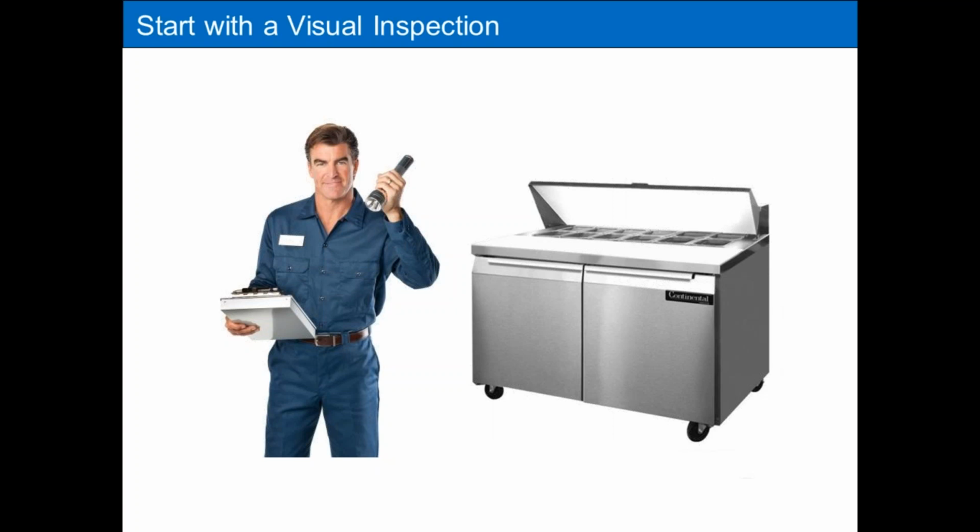A lot of times the cabinet's going to be in a food lineup. Pull it out, look behind it. A lot of times you'll see a plastic baggie right on the condenser. It's sucked in, not wax paper, but a plastic bag sucked in and blocking the condenser. It's a quick fix. Pull the bag out and the unit probably starts running okay.